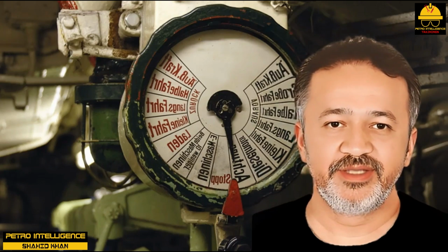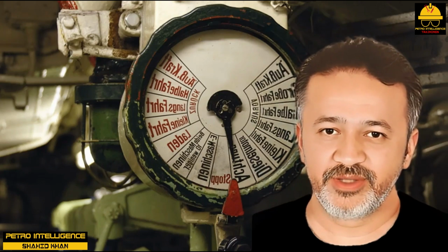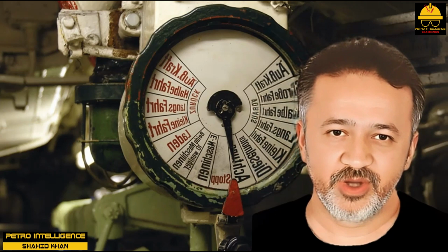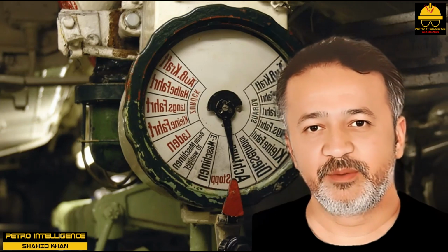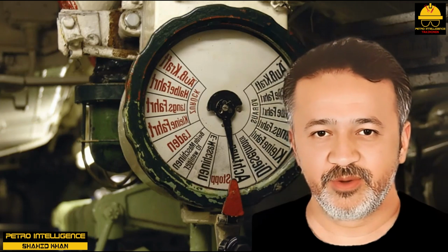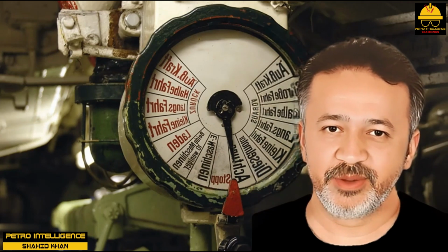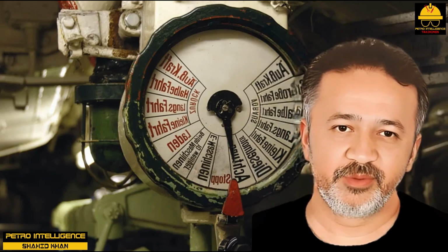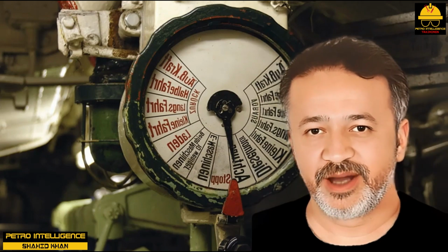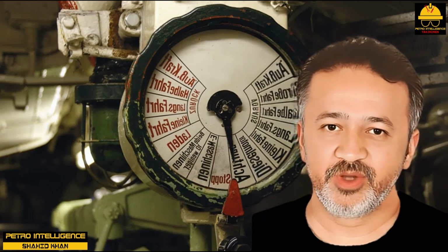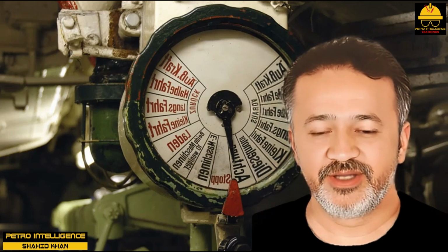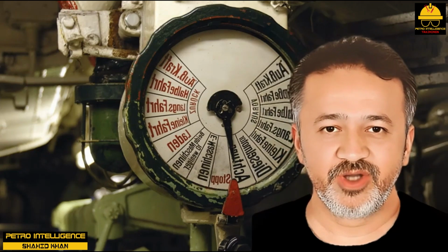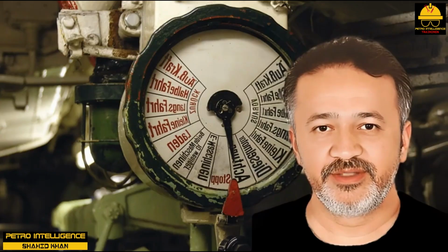Once the system is online, the console technician will insert the set point on the controller and place it in auto. This procedure enhances the time it takes to bring a unit up to steady state and produce a high-quality product. Automatic control uses all 5 elements of the control loop in a dynamic system that measures, compares, and attempts to control a specific process. Process units may have hundreds of control loops that make it possible to control level, pressure, temperature, flow, and a variety of analytical processes. Automatic control allows a process technician to control a much larger and more complex arrangement of process systems.